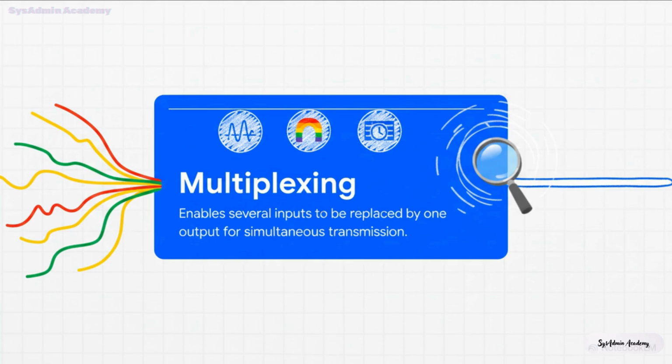And that brings us to our core definition, multiplexing. It's the networking technique that enables several input signals to be combined and replaced by just one output signal. This allows two or more simultaneous transmissions to happen over a single shared medium. But there's a strict rule here. To avoid total chaos and data collision, all of these signals absolutely must differ in some way. They either need to occupy a different frequency slot, a different wavelength slot, or a different time slot.